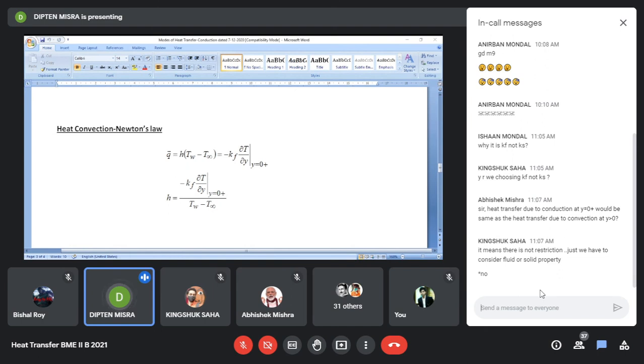In fact, what we know in this type of problem is the surface temperature and the free stream temperature. Now, through some rigor, through some exercise, we have to calculate the value of this thing. That is the subject matter of experimental identification of the gradient, or theoretically you have to find out the gradient. Because to find out the value of h, as we see, we refer to the temperature value on the boundary given by TW and the temperature gradient inside the domain.